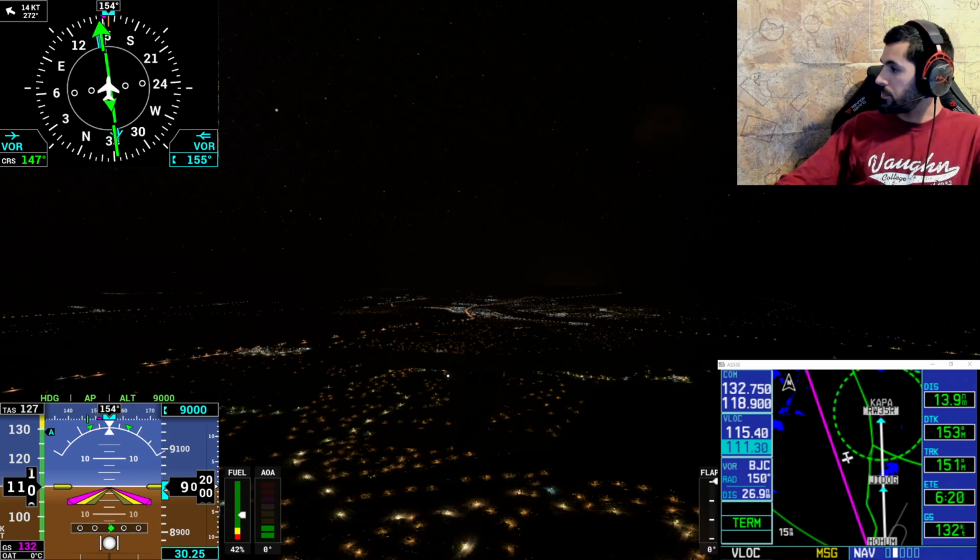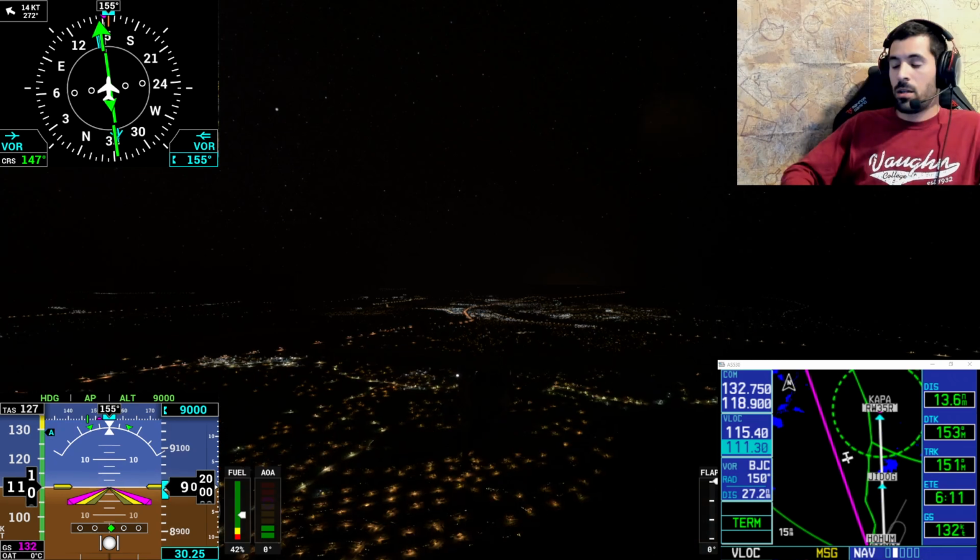Now, typically if you're going to use one VOR, especially for instrument approaches, you're going to want to use two. It's how you triangulate your position. And typically we would know we are over XB by using a second radial, which is Falcon VOR. But I'd kind of have to go in the aircraft and manually put that one in.